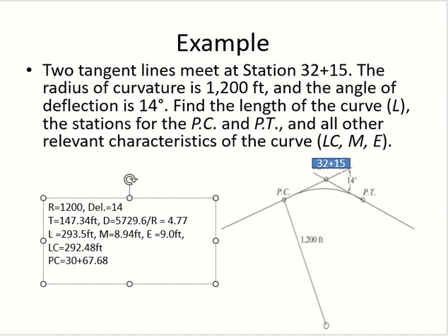Okay, so now I know how far is this point from the reference. And how far is this point from this point? PC plus C. Okay, from PC to PT is what? The curve, right? From PC to PT is the curve. So the length of the curve. So you will add the length of the curve to get PT.